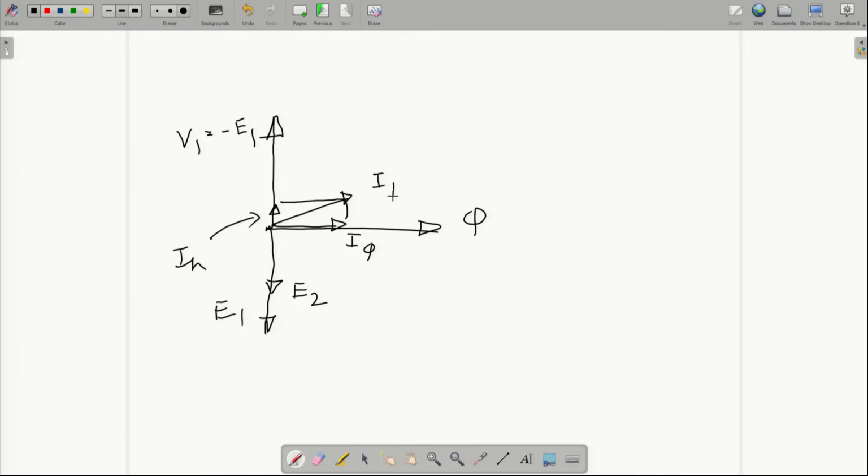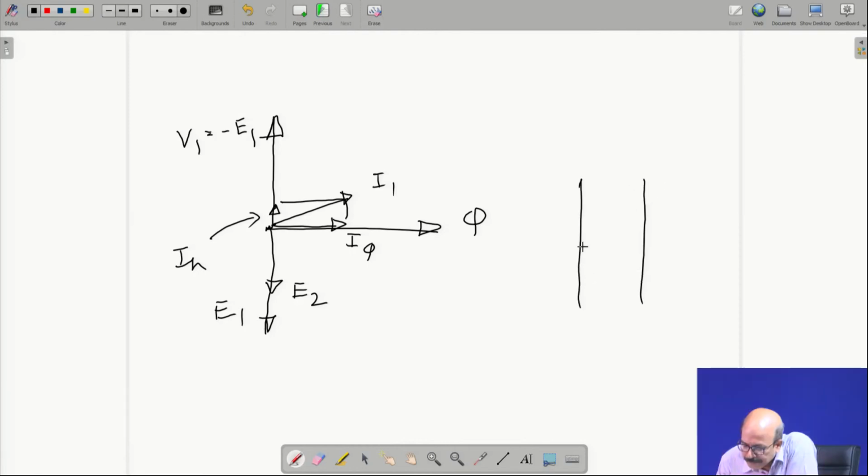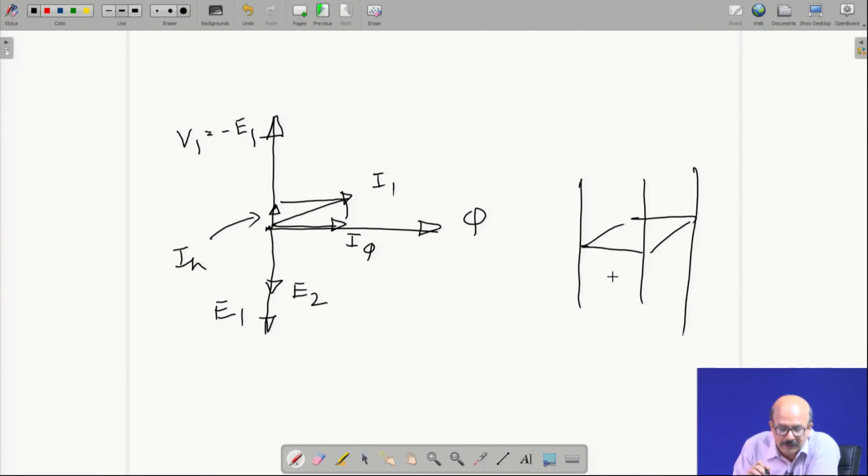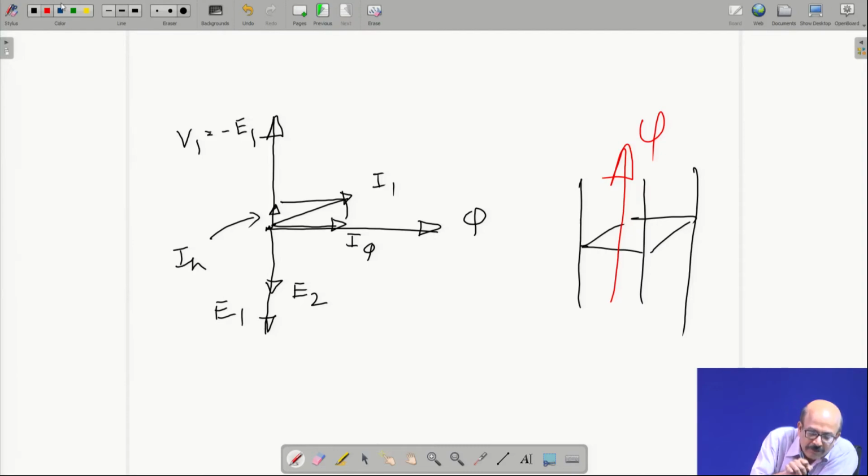In the transformer core, other than hysteresis loss, you also have eddy current loss. Eddy current loss, you all know, if you think of the core area, when the flux is oscillating, some positive, this side negative, oscillating, you can clearly think of it, because the core material is not insulating material.